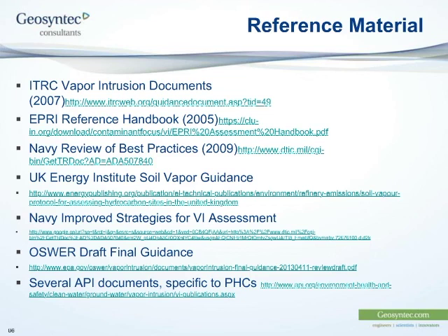My, how much groundwater remediation by pump, treat, or sparging encourages production and release of vapors? Okay, so if you're doing groundwater extraction, then you create a drawdown cone. That lowers the water table. If you lower the water table, the zone that used to be saturated is now unsaturated, and a continuous gas phase will develop. But the pore moisture that's left behind could still be containing VOCs. And so they now have a continuous gas phase to vaporize into and can migrate through.